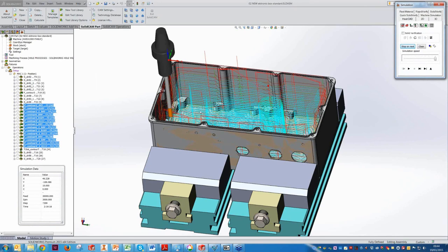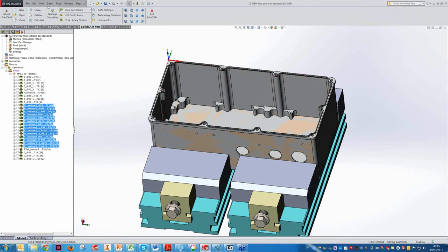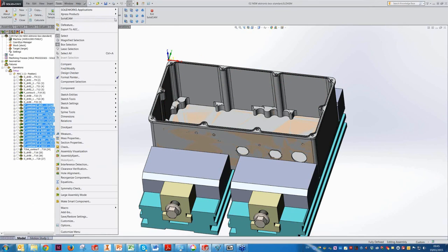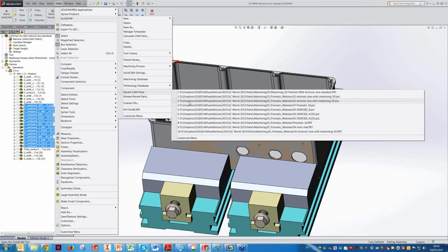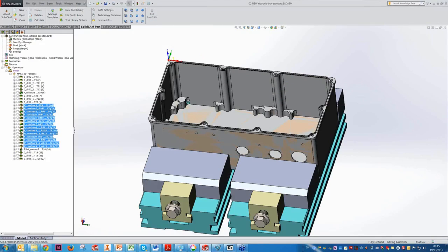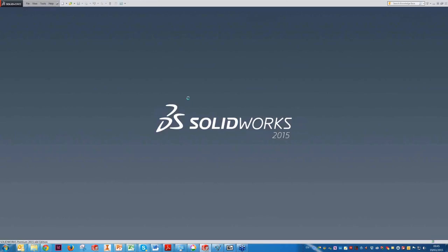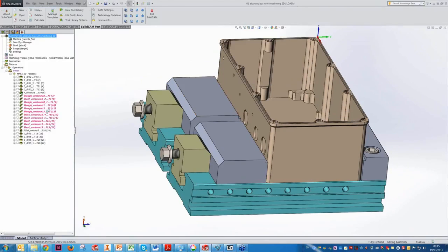So it took, in standard 2.5D milling, to finish this electronic pocket, 2 hours and 16 minutes. Let's look at this same part if you do it with iMachining 2D. First of all, you see immediately we have fewer operations in iMachining 2D as opposed to standard 2.5D milling.